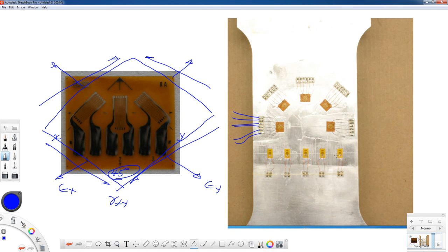And down along the bottom are a set of linear strain gauges that helps us determine that we have a uniform strain distribution before we get into this weld zone that's around here. It's hard to see, but there's a kind of a big circular weld right in here.